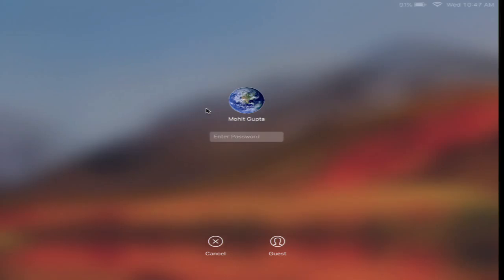So it is again an anti-symmetric solution. As you can see, it will be positive in the first quadrant and negative in the next. So if this is your section and this is your coordinate frame, then this will be positive in this quadrant because x2 and x3 will be positive. It will be negative here, positive here, and negative here. And these positive and negative signs are associated with displacements out of plane.